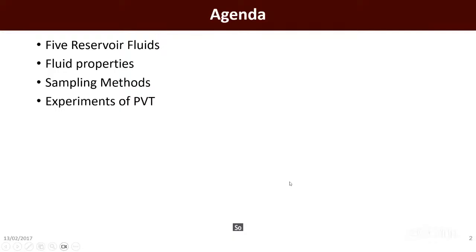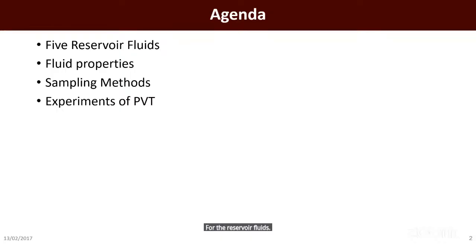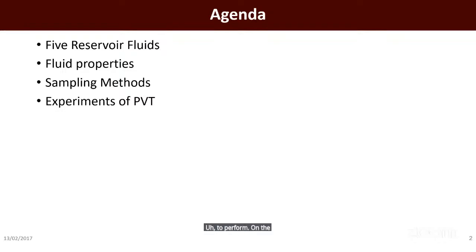So we are going to discuss today the importance of the PVT, the major classification of reservoir fluids, the fluid properties that we are interested in for the reservoir fluids, the sampling methods in order to get a sample to be analyzed to get the PVT, and the experiments that we are going to perform on the PVT samples.